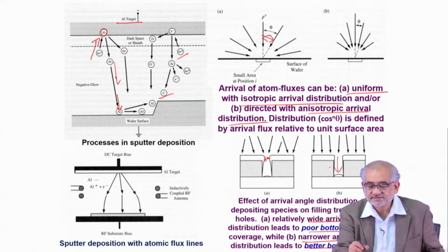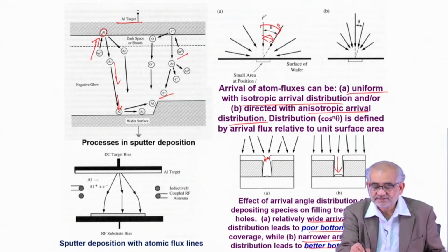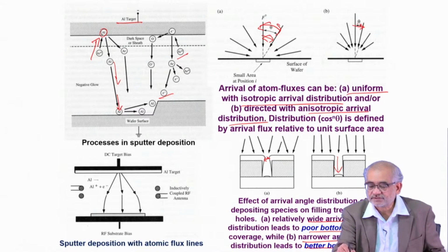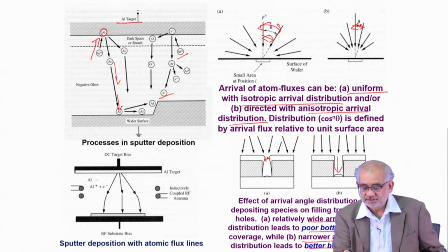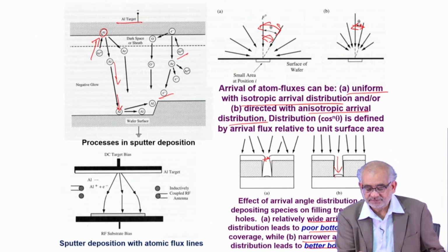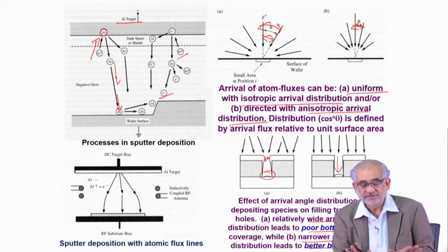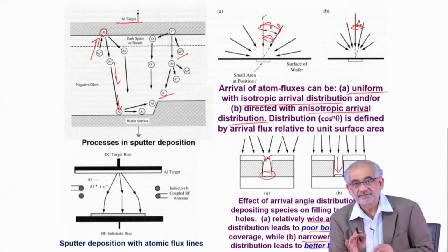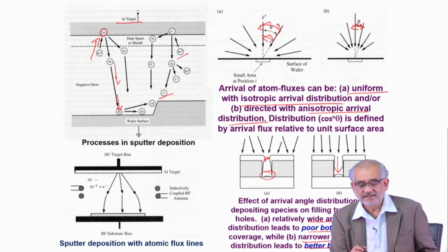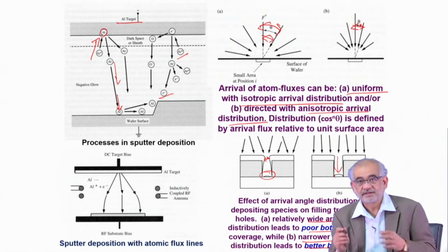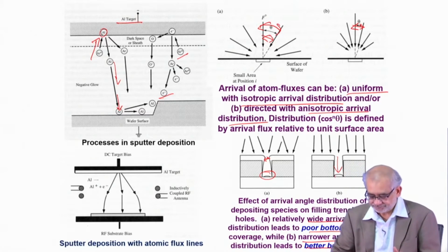So in that case, we may use either wider or shallower angle of deposition. And that's how we can make sure that we actually can create wider coverage here and not end up having incomplete coverage at the bottom of the trench like here. So depending on the features that we want to develop and the dimension of the features, we have to select the exact arrangements for deposition.